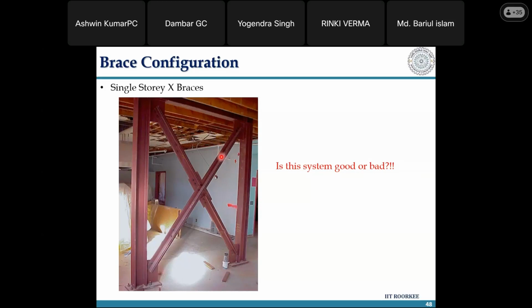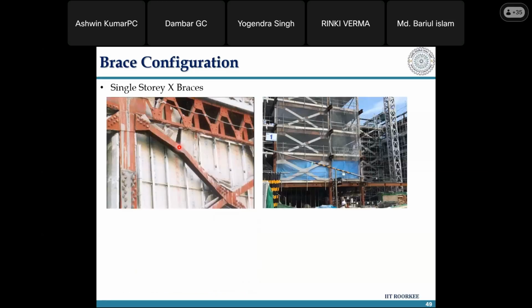So for an X-braced frame with the connection at the center, the effective brace length, or the buckling length, reduces. So it will buckle like this in this location, and the hinges will form at the mid length, or the length is given by the code, but that will form there. This is an example of that X-braced frame.